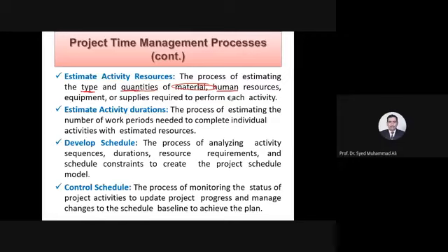It can be any number. I'm just giving you randomly without paying attention to whether this is too much or too less. Then, for example, mason will be 400 rupees per hour. When you said 1,000 liters of petrol, then the cost per liter is this much. For example, 1 liter is 120 rupees or 110 rupees per liter. So all these things need to be defined in the software. And when you put it in the activity chart, you will start getting what resources are deployed to this and what is the cost of these resources for each and every activity.